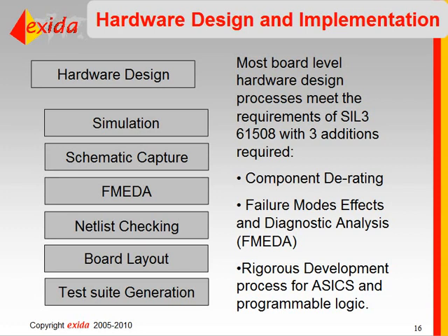So the component derating essentially says that for each component, you cannot operate that component at its maximum rating on average. You want to derate it. So as a guideline, it says you want to operate below, say, a 33% derating, so that the component should not operate more than, say, 67% of its full rating on average. So this will significantly increase the reliability and the life of the overall product, and that's the main reason for this requirement. The 67% is a guideline. It's not a hard and fast rule, and if you have good justification, you can use different values for different types of components.